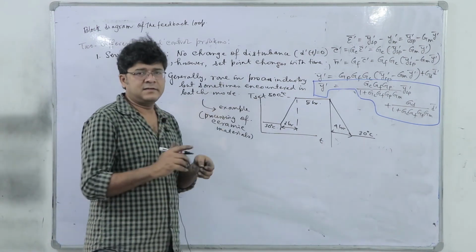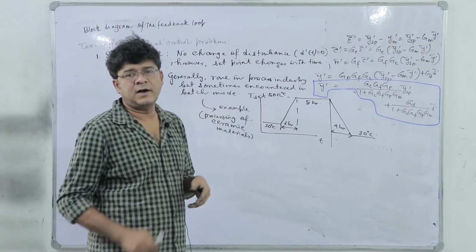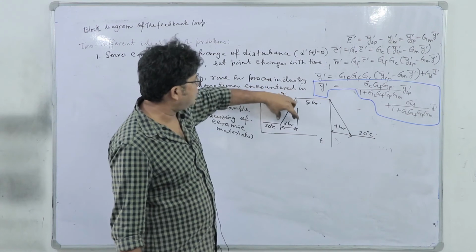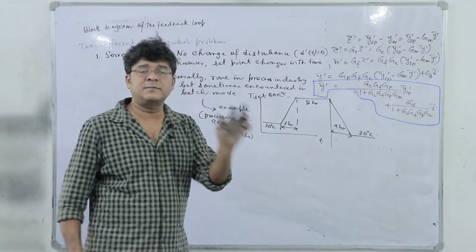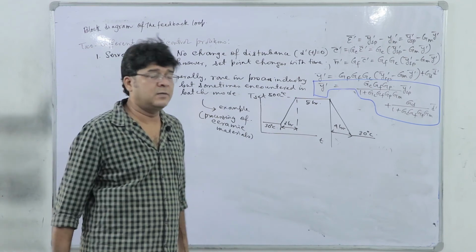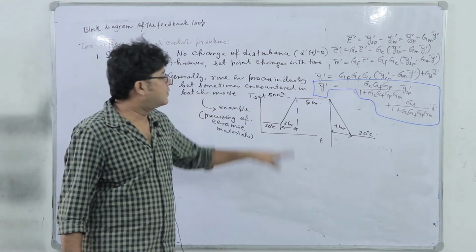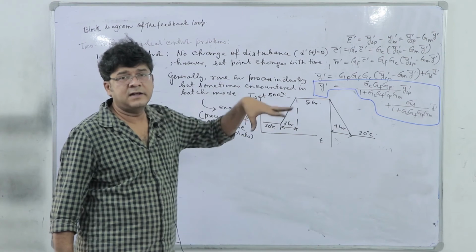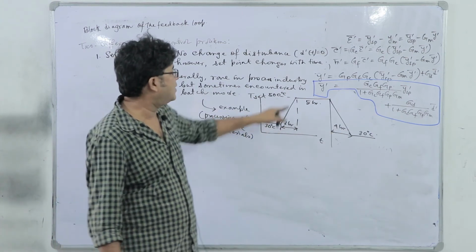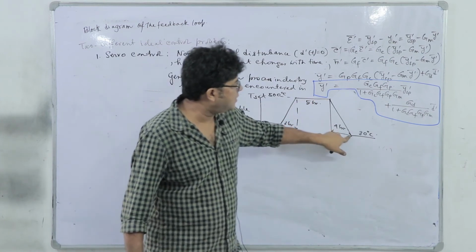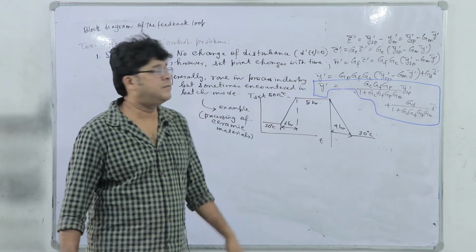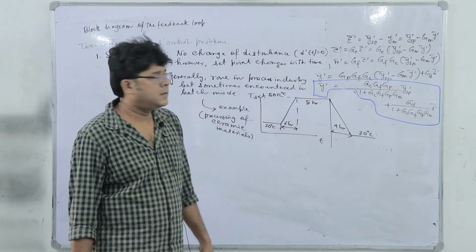Now, in the furnace, it should be a temperature controlled furnace, where the temperature initially must shoot up to 500 degree over a duration of 3 hours. So, there is a specific ramp with which the furnace temperature must change. Okay. So, furnace temperature here is a set point, and which must be actually going through a dynamics, then it should remain constant, and then it should decrease again to 30 degree. So, this is a typical example of servo control.